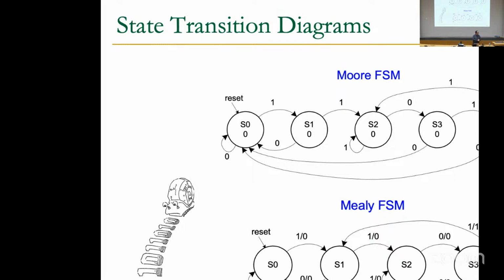Is it clear? Question? Okay, sounds good. So what are the trade-offs here? Yes? Well, I think you can do the same with Mealy, but with Moore you might need more different states. Great, yeah, that's one of the trade-offs. A Moore FSM always has a higher number of states, so that comes with some overhead. But is there anything where we think Moore is better than Mealy? Yes? It's easier to encode. It's easier to encode, yes. It's also sometimes easier to reason about.